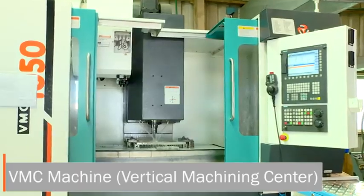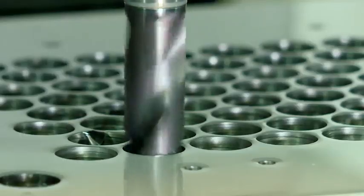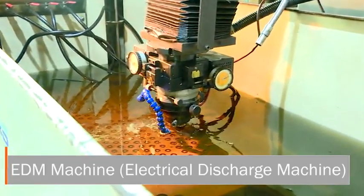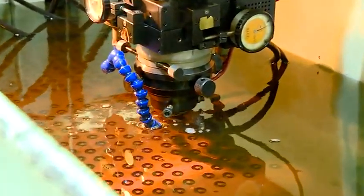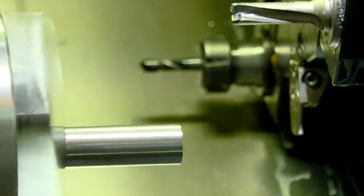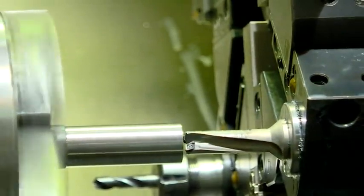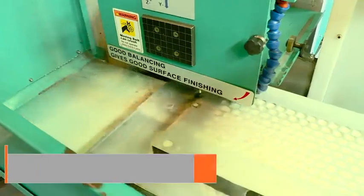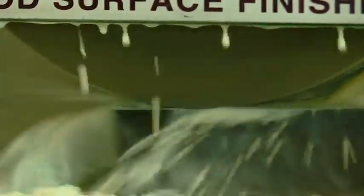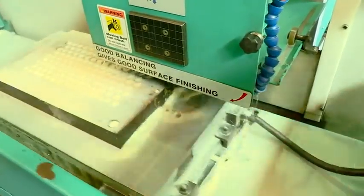For example, the VMC machine has vertically oriented spindles and is used for cutting workpieces mounted on its table. The EDM machine uses carefully controlled electrical sparks to cut through the workpiece, while the CNC lathe machine rotates the workpiece on its axis to perform various operations such as cutting, sanding, knurling, drilling or deformation. The surface grinding machine is largely focused on finishing processes using, for example, a rotating abrasive wheel to smooth the flat surfaces and give them a more refined look.